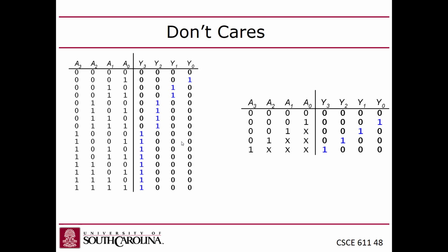You guys with me? So what I'm saying is that these don't cares don't really help you much for minimizing circuits like output don't cares do. You guys with me? So this is more of a shorthand here. If you have don't cares in the output, it means that you don't care what that output value is, and that is something that you can take advantage of in a K-map to make the circuit simpler, right? So there are input don't cares and output don't cares. I'm emphasizing that because that's something that used to confuse me.